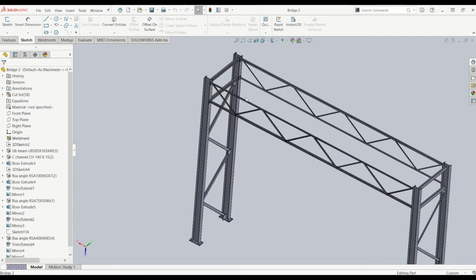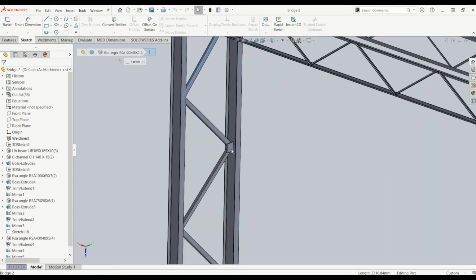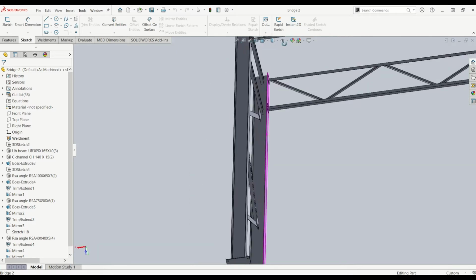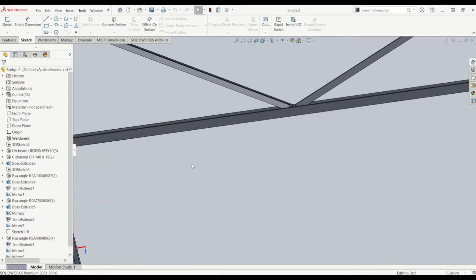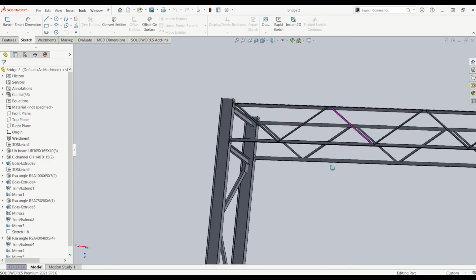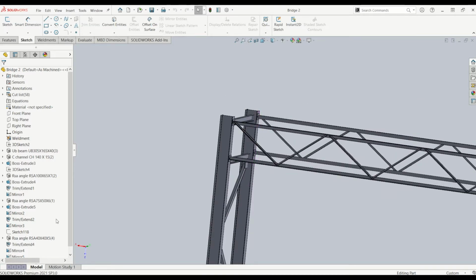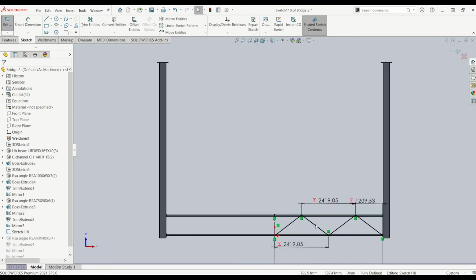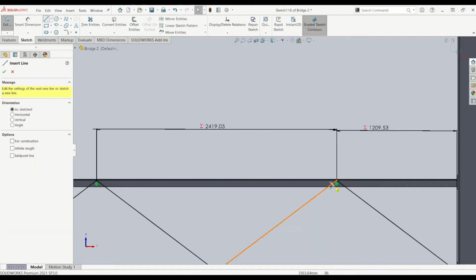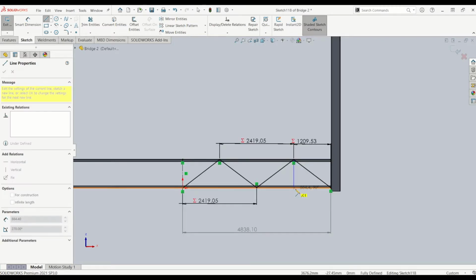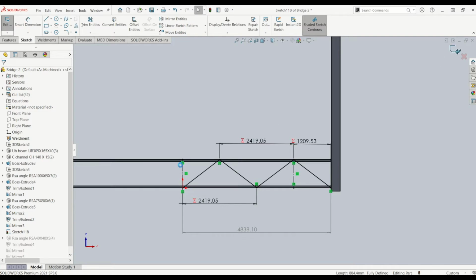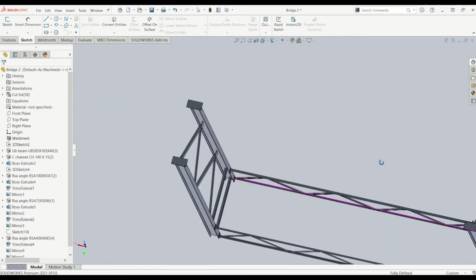So just to get started and do the cross members, it's very similar to how you do the struts with the plates on the legs. I'm going to click the sketch here, which is what I used to make the reinforcement struts, and I'm going to do a construction line from there to there, so I know the dimension I need to put my plate on. So just make that construction line, exit that sketch, flip it the right way back around again.